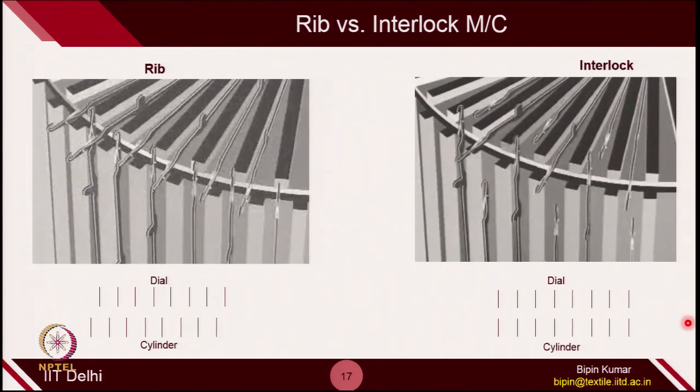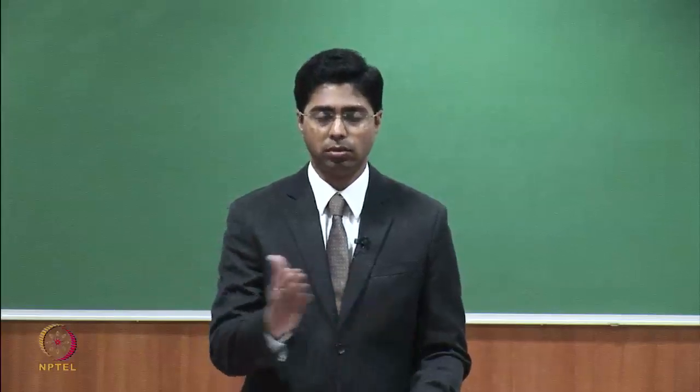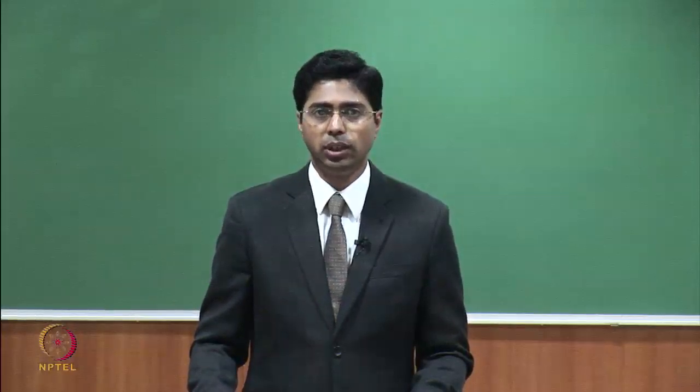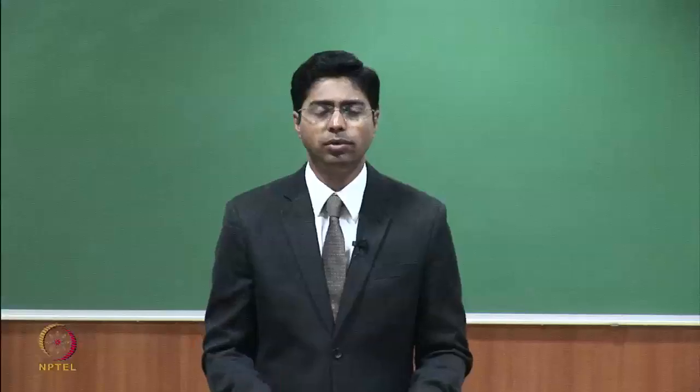So in next week when we will see the different fabric structure in weft knitting, then you will realize in rib category you create a double jersey fabrics which has a different property, but in interlock machines you again create a different kind of fabrics which has different property compared to double jersey fabrics which is created on rib knitting machine. So the fabric which is produced by these two machines are completely different, and that we will look at next week. Let us see positioning of these needles.